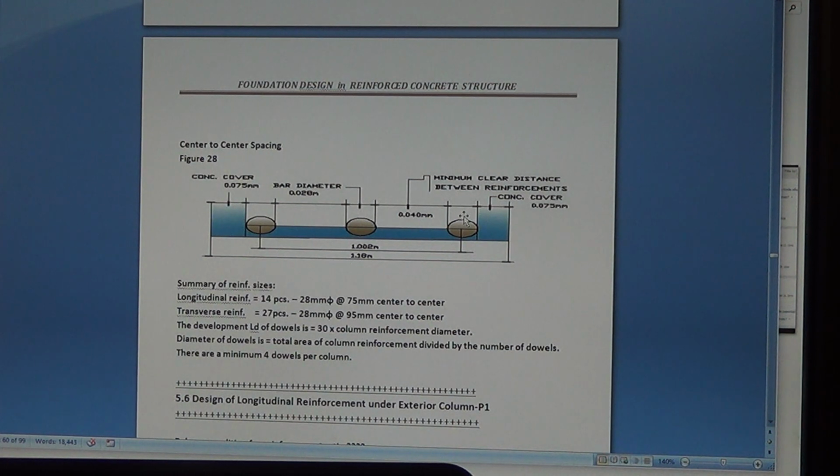When you remove a bar from the actual supposed placement, you have to remove at least 3. Remove the 3 and bundle on the other bar on top of it. To bundle it, sometimes we use welding or just tie it with wire, the tie wires, so that you can have a clear span.